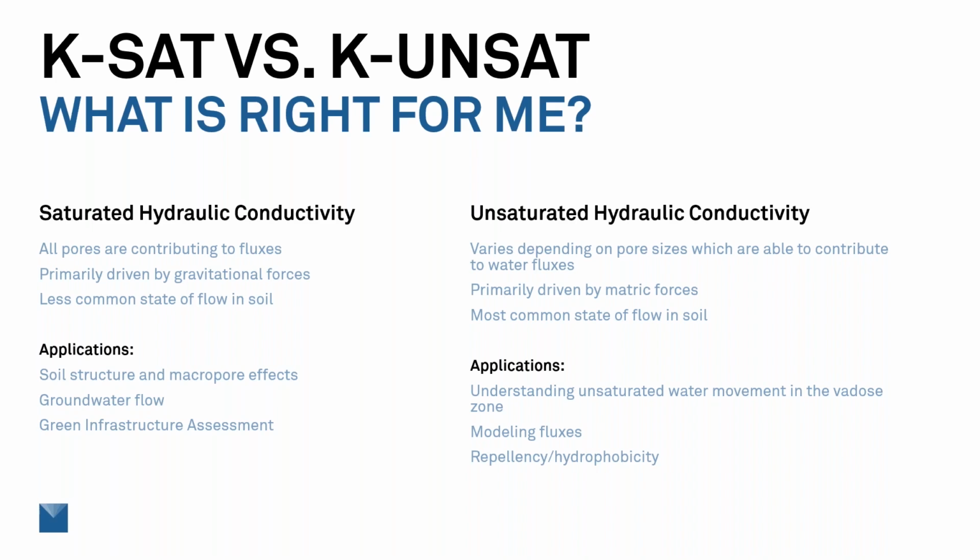This saturated hydraulic conductivity is primarily driven by gravitational forces. So it's just something to keep in mind. But another piece that's kind of important to keep in mind is in most sites and most conditions, this is a less common state of flow in soil. So if you're trying to understand water movement throughout a season, you're going to need to know more than just saturated hydraulic conductivity. Now let's jump over to unsaturated hydraulic conductivity.